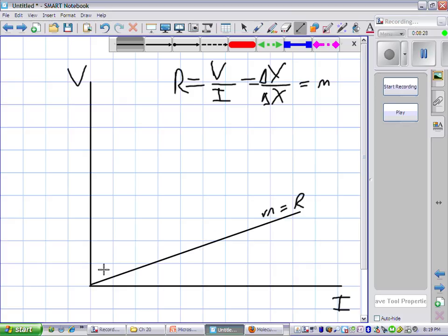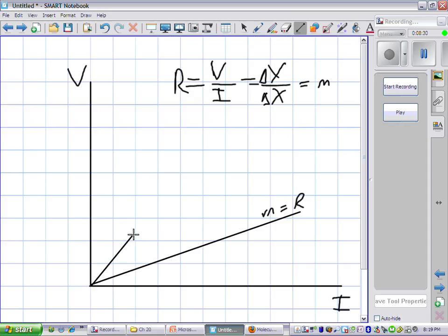So you draw another circuit, and you'll have a bigger resistor in that circuit because the slope is larger. You'll see voltage here, and you come across and you'll find the current, so a high voltage will be a higher current, low voltage will be a lower current, and that follows this relationship of Ohm's law here. R equals V over I. And that's how the graph works. The slope equals the resistance.